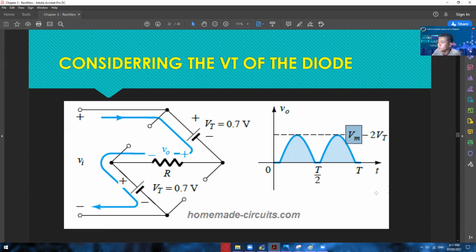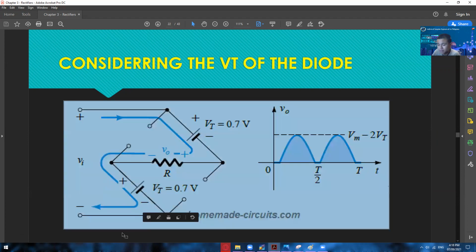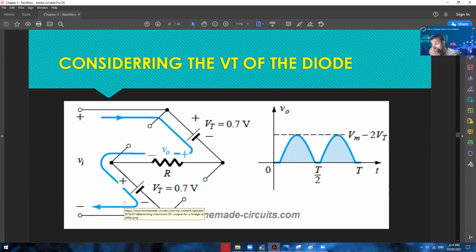So Vm minus twice the VT. You can do this if you have the same silicon diode on those diodes. But if you have germanium on the other one, then of course you have to change this into negative 0.7 and then negative 0.3. Okay, negative 1 volt. All right.